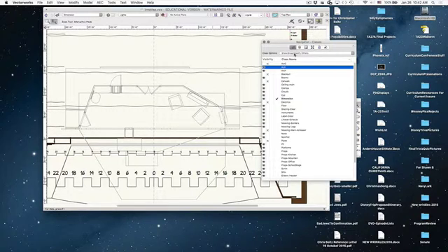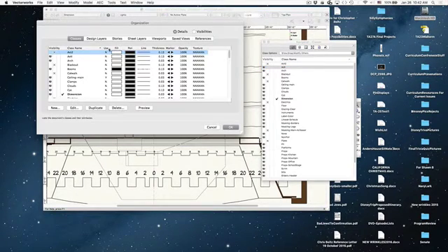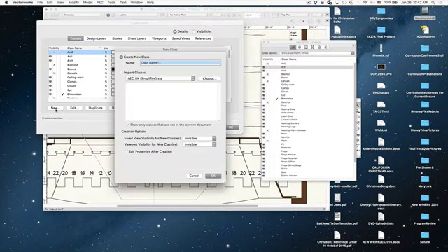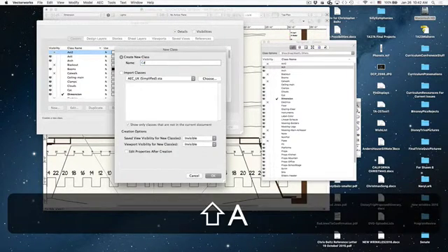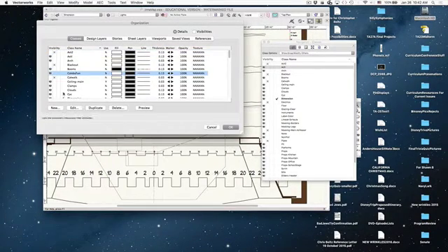Be organized. A lot of ways with Vectorworks you can turn things on and off. So if you have something that you're trying something out on, I would put it on a separate class called Caleb Has Fun. Okay? That is just a separate class that you're not going to use, or that you're going to use for doing a little experiment, but it's not part of your finished product. Okay? So to add a new class, I'm going to double click here. And to add a new class, I'm going to type new. And we're calling it Caleb's Fun. Okay? And I click OK.